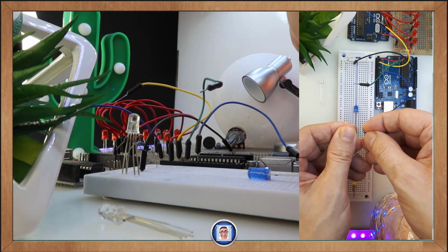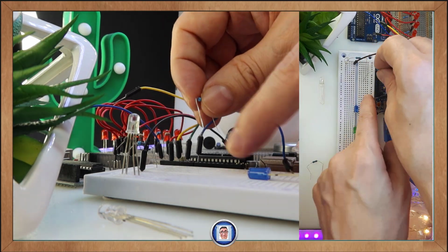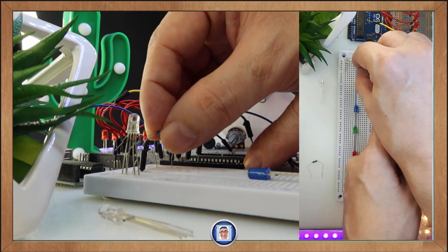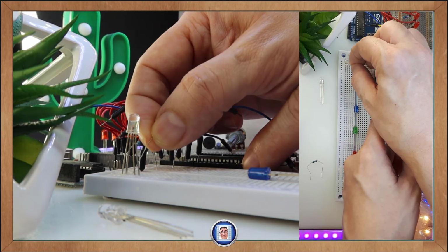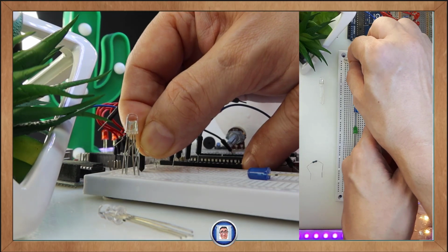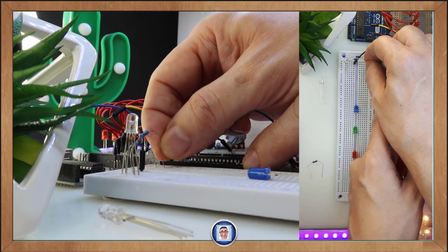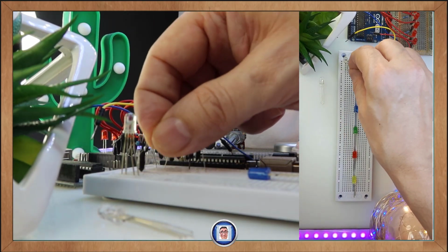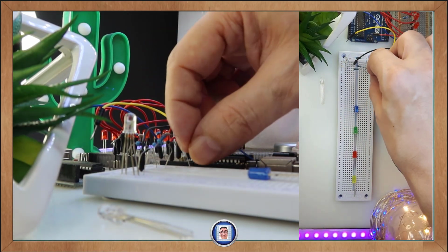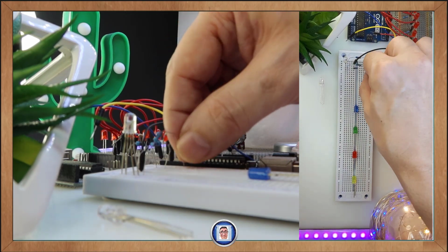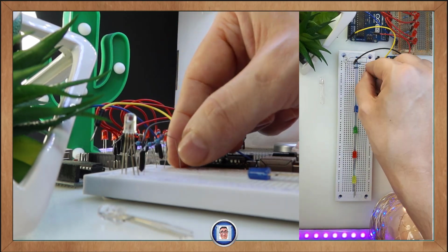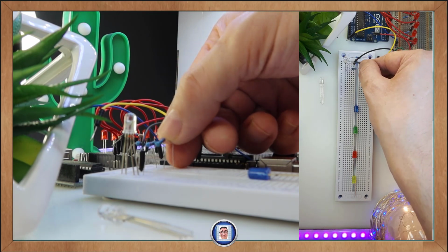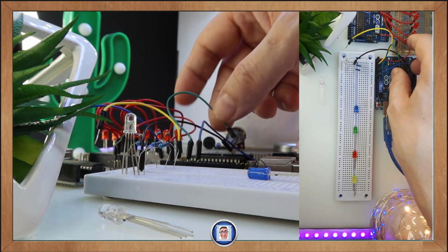If you remember, for our circuit, I chose not to match the exact resistor. I went above with all of them being 220 ohms. And this, although it makes the LED a little bit dimmer, will prolong the LED's life. I do have an upcoming video about resistors to find the correct wattage and so on, if you like. As you can see here, I'm having a little bit of difficulty putting the last one in, but here we are. At this point, we can now connect the corresponding wires.